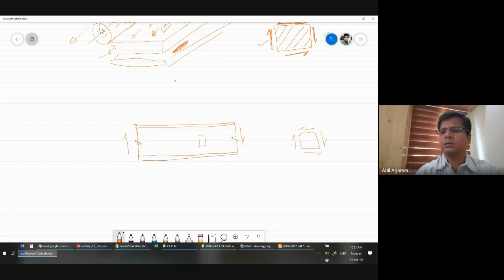If you reorient yourself by 45 degrees, what you will see is that this shear can be represented as a tension here and a compression here, right? This is just Mohr circle transformation. You are familiar with this transformation. You just need to use Mohr circle to get these stresses.